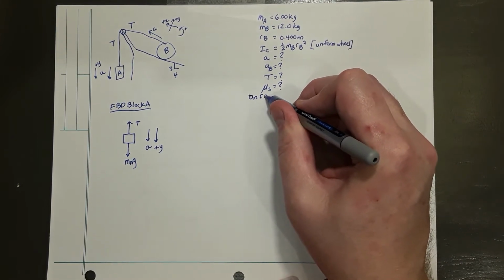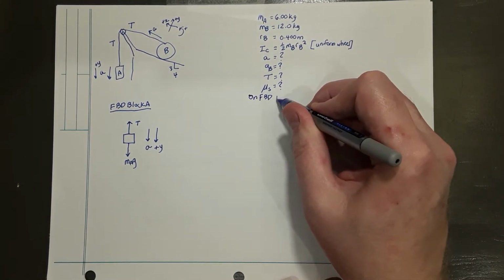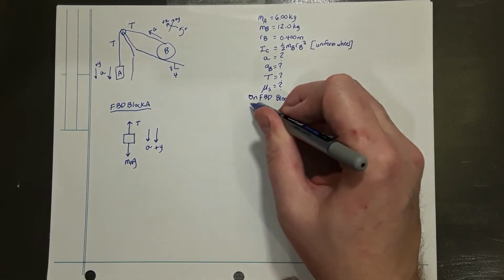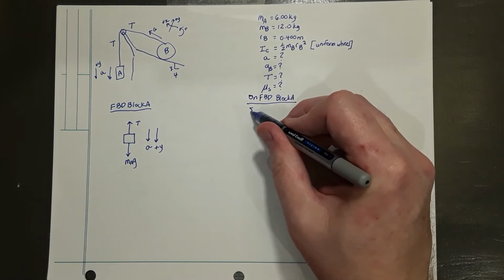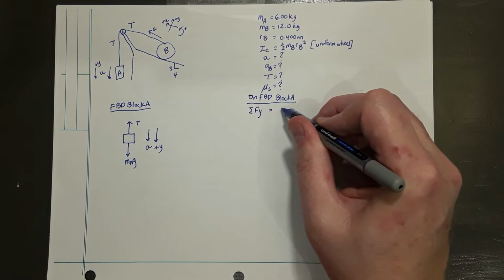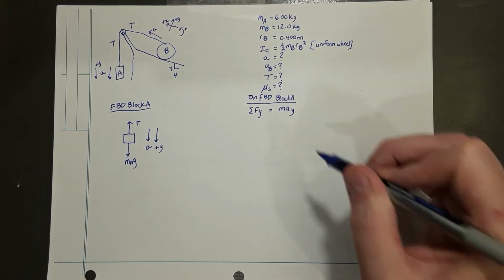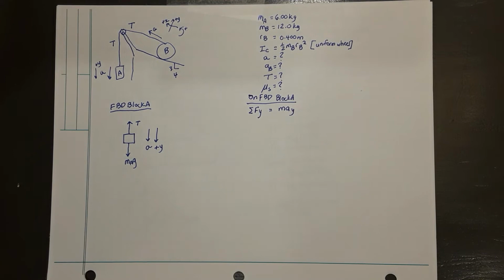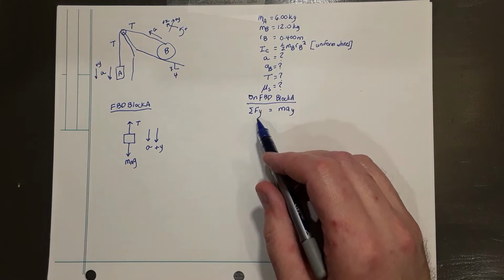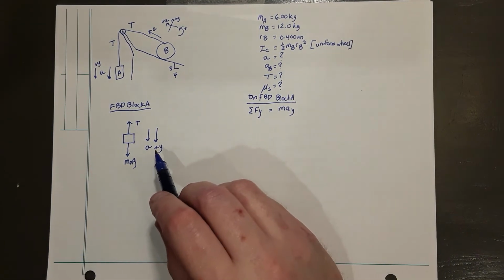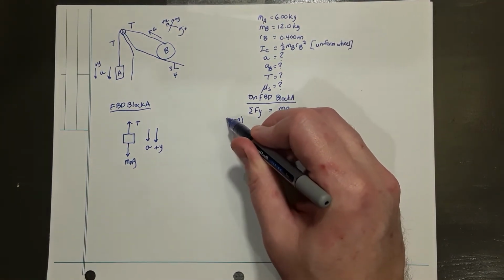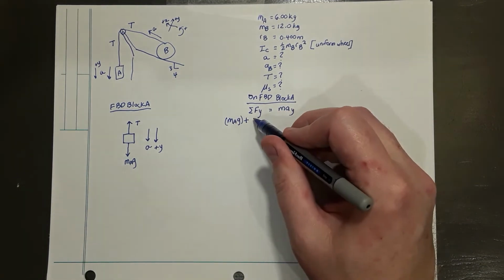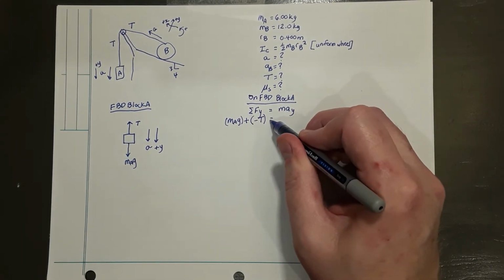when we analyze the free body diagram of block A, the equation that applies, step 4, would be net force equals mass times acceleration. Net force in the y direction is mass times acceleration in the y direction. You do the left-hand side of this expression independent of the right-hand side. Because down is positive, my weight vector is going to be a positive vector component. And tension will be a negative vector component.